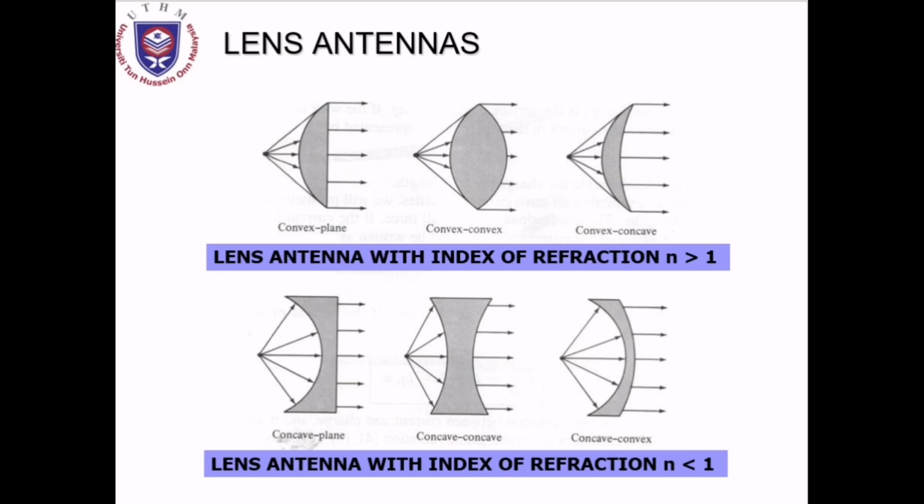This is uncommon, a bit rare, the lens antenna, because it is quite hard to fabricate and also hard to design. With a lens, for example, you have a source here. We can redirect the electromagnetic wave by using the refraction of the lens material over here.